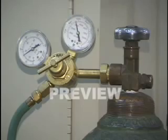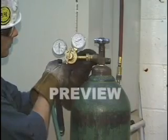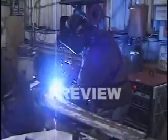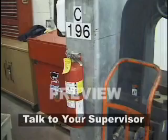Before any connections are made, inspect the cylinder carefully. Do not change, modify, repair, or tamper with the pressure relief devices on cylinders. During welding or cutting operations, keep the work area clear of debris and keep a fire extinguisher nearby. Talk to your supervisor if you have any questions or concerns.